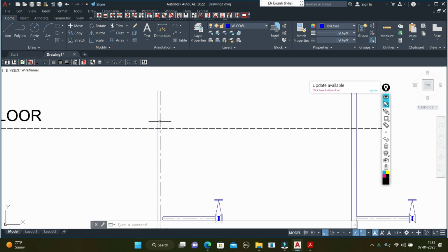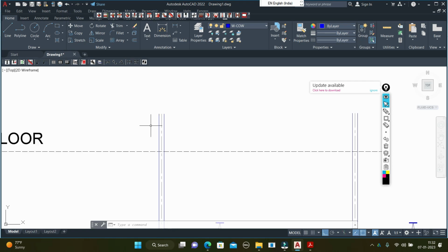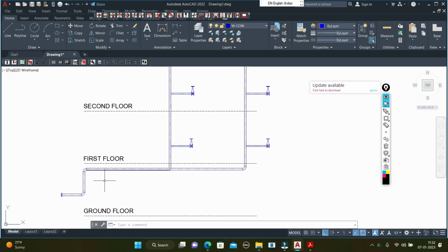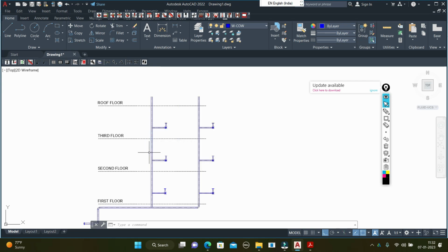And for this one we take, here, a controlling gate valve and an air release valve, air relief valve, because if they pump the water, then air can be trapped inside, so the water will not flow as fast.